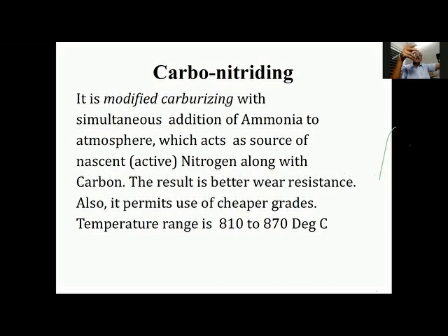The other advantage is because of the lower process temperature, the distortion is less. The noise generated by carbonitrided gears, you will find, is invariably lower compared to the carburized gears which are processed at higher temperature. Next, please.